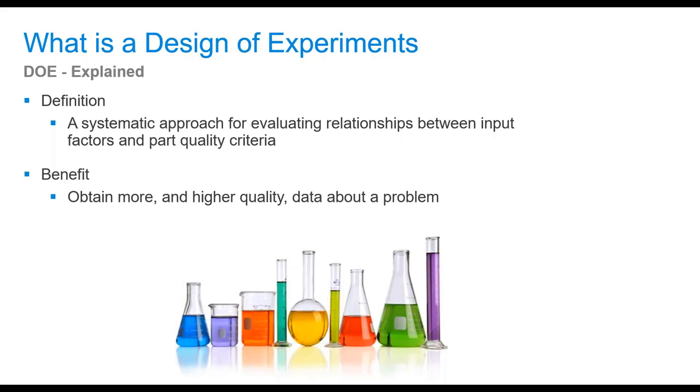Today's world is all about data, so when viewing a DOE in the field of scientific injection molding, this is how you can log a tremendous amount of data to help with improving your molding processes. It provides a holistic view of how each of the machine settings influences the end product. This enables the process engineer to hand over those influencers to the manufacturing team when the mold goes into production, to create more informative process settings and instructions to better prepare them for handling part quality concerns that may appear during production.